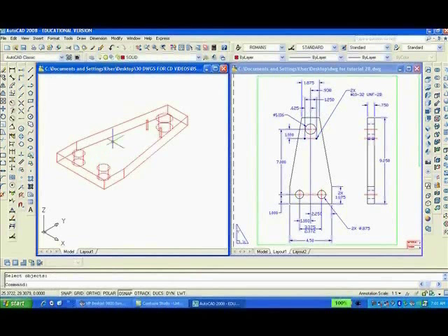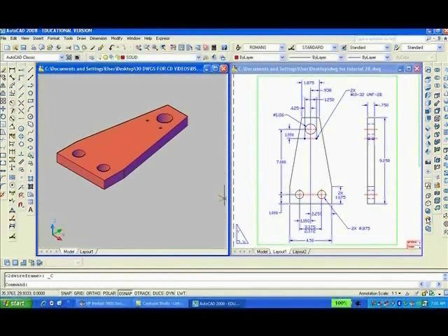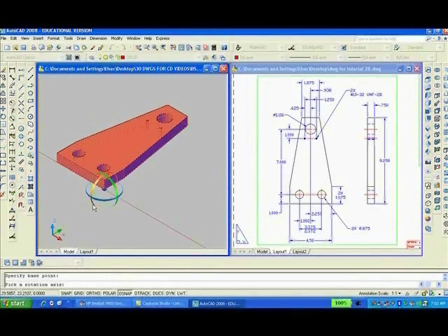Enter and see what it looks like. It looks okay, so we'll Z, well, I think perhaps we'll want it to stand up. So I'll hit escape and I'll go to 3D rotate. Pick a point, select the red axis and type 90. Enter.